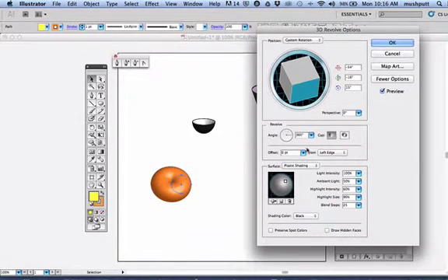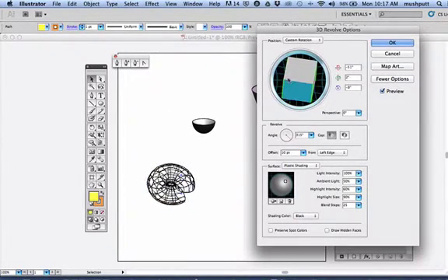It's a donut. But we need to open up the hole in the middle just slightly. So we use offset to separate where these points revolve. Offset simply opens up and separates. So again, you might try to take a tiny chunk out of your donut by using less than 360 if you choose to do that.